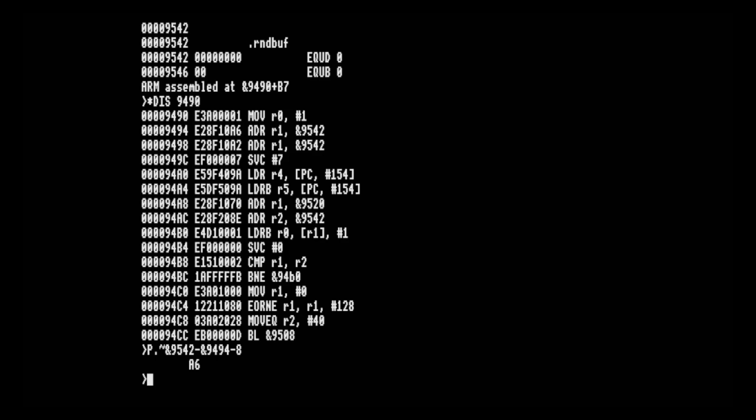The rest of these numbers, the E28, is all part of the add opcode and the condition codes if we're using conditional execution, that kind of thing. The F is one of the operands that we're adding together, so 15, because one of the operands is the program counter. The 1 is the register we want to store the result into. So this all starts to make sense.